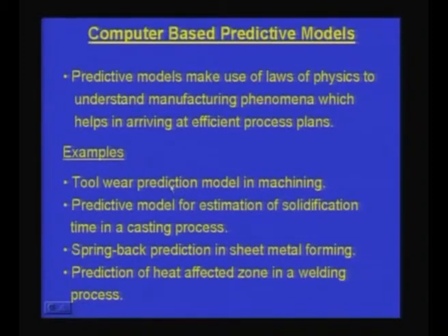For example, a process planner who is trying to prepare a process plan for a component which has to be machined would be interested to know what would be the tool life. Suppose I am using a tool where there is an insert and this insert has to be replaced after certain time.